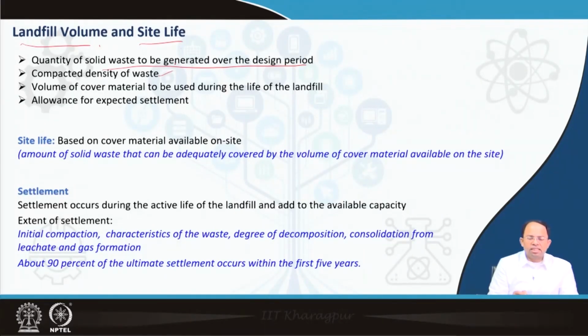Then, compacted density of waste for the kind of waste that is generated in that particular area. Volume of cover material to be used during the life of the landfill, because as we have discussed earlier, this sometimes determines the life of the landfill. If soil is not available, it would be too expensive to import soil from outside. Allowances for expected settlement: a lot of settlement happens over the life of the landfill. That has to be considered.